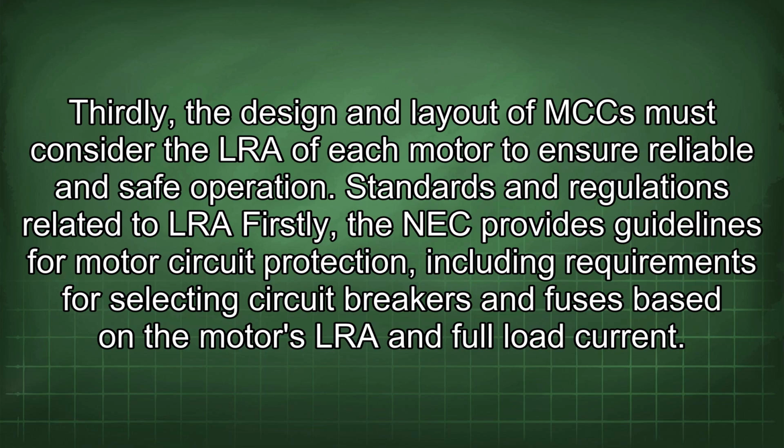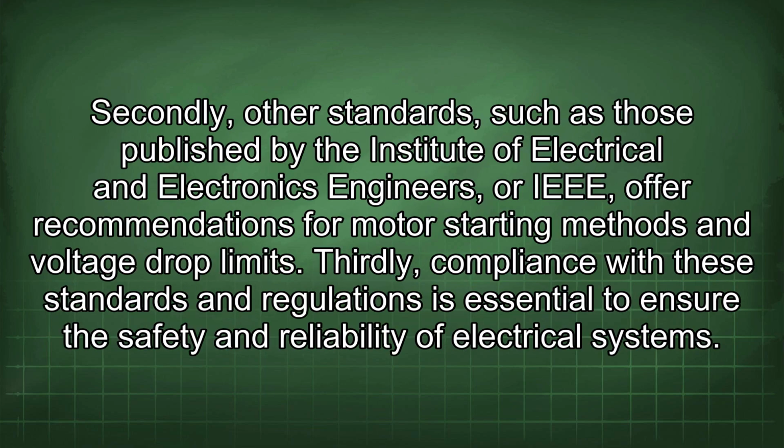Standards and regulations related to LRA. Firstly, the NEC provides guidelines for motor circuit protection, including requirements for selecting circuit breakers and fuses based on the motor's LRA and full load current. Secondly, other standards, such as those published by the Institute of Electrical and Electronics Engineers, or IEEE, offer recommendations for motor starting methods and voltage drop limits. Thirdly, compliance with these standards and regulations is essential to ensure the safety and reliability of electrical systems.